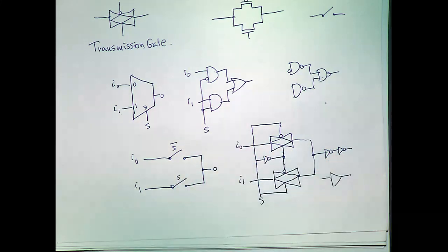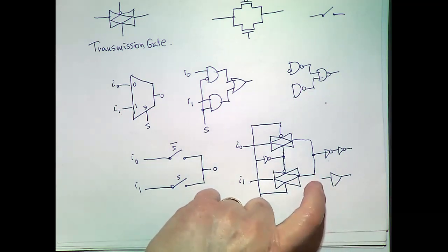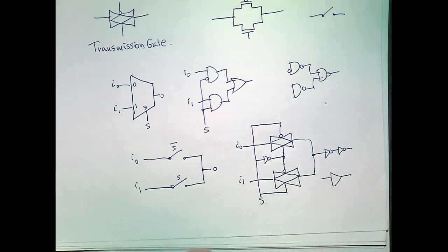In a schematic that really has no resistors, capacitors, or other types of things, a symbol like this is just a way of renaming the two wires. So sometimes you've drawn a diagram and you have a net named A, and you have another net named Alfred, and you would like to connect A to Alfred. Your schematic was going to complain, and so you can't connect two separate nets.